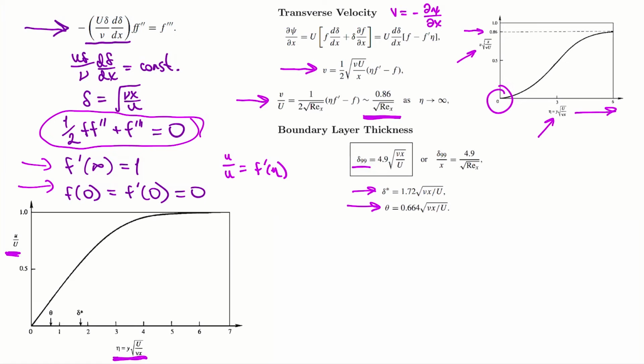We'll note that the local Reynolds number here, referred to as Reynolds sub x, is defined as free stream velocity times the x location along our flat plate, divided by nu. We see a prediction of parabolic growth, right? So this boundary layer thickness is a function of root x in each of these cases, and that's in good agreement with experiments as well.